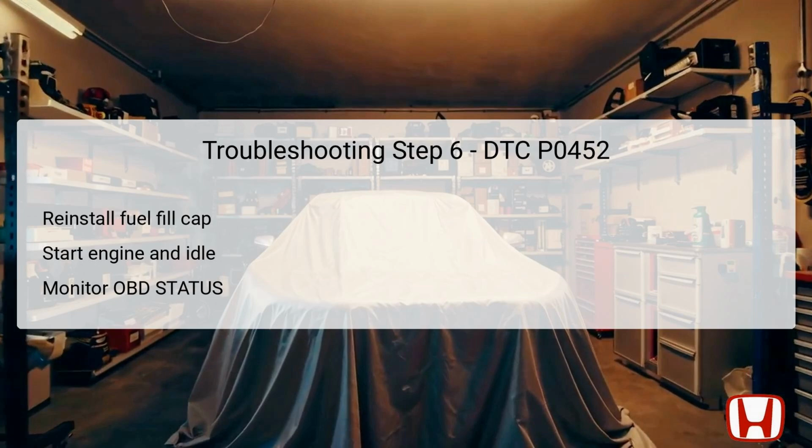In this troubleshooting step, you will need to reinstall the fuel fill cap securely back onto the fuel tank. After ensuring that the fuel cap is properly seated, start the engine and allow it to idle. It's essential to give the engine sufficient time operating at idle so that the onboard diagnostics can adequately assess the system's conditions.